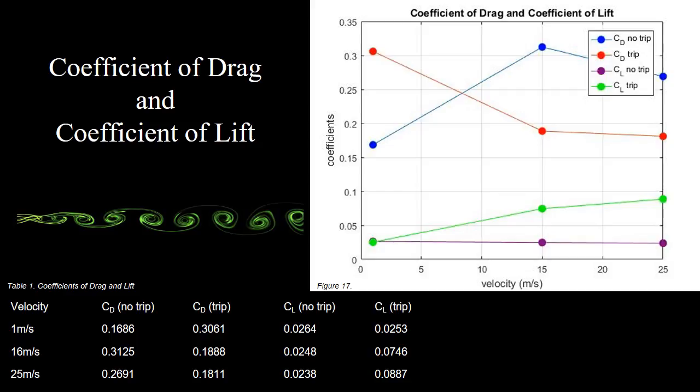Putting the pressure points at the center will cause errors due to the stagnation pressure accounting for a much larger area and the pressures at the top and bottom being excluded. The pressure drag coefficient for the laminar case acts differently to the two transitional cases, increasing with the addition of a tripwire. It is possible that the flow was tripped too early in this case, causing the separation to occur early and therefore increase the drag felt by the cylinder.